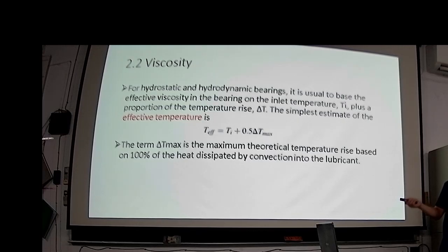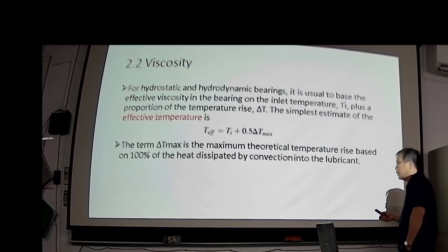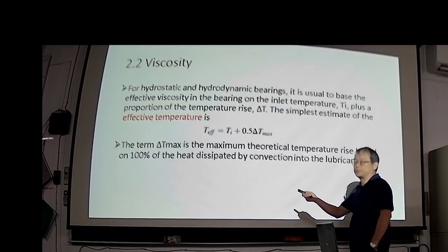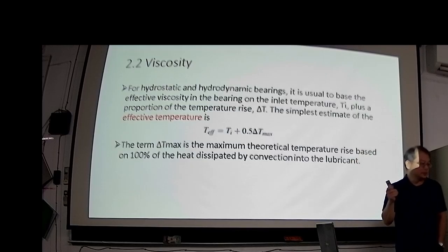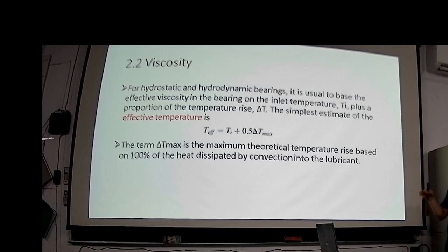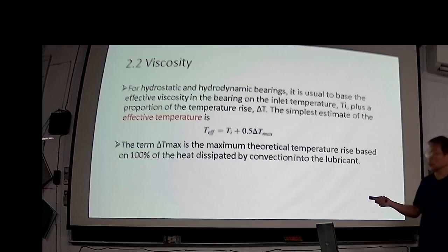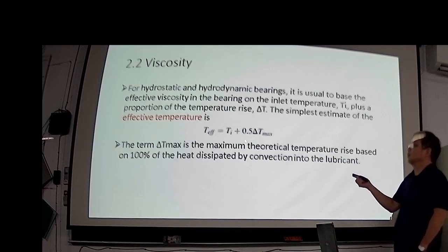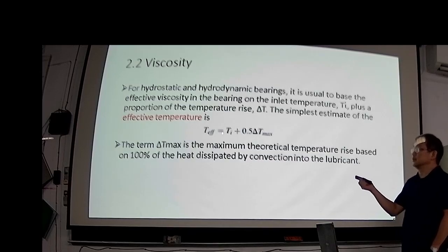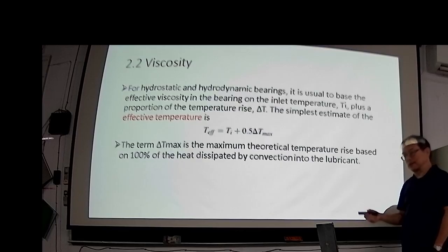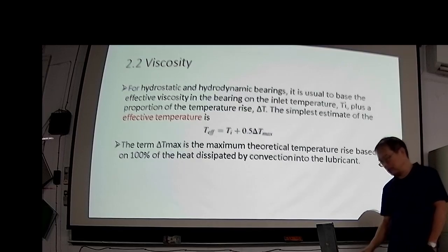you are overestimating the temperature rise for the lubricant, because in reality some of the heat is dissipated by radiation from the oil to the air. Not 100% of the heat dissipation will get into the lubricant. So you are estimating the effective temperature a bit higher than the real situation.